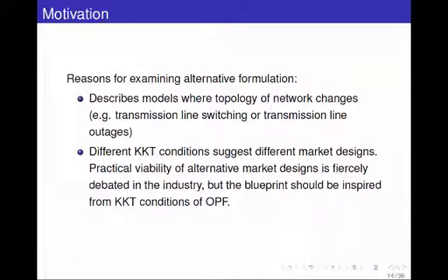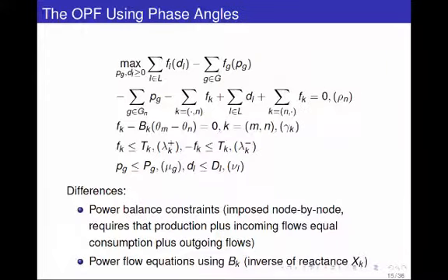And there's huge debates on which dual problem we should be using. Okay, the other reason for taking a look at this model is that we can actually model changes in the topology of the network. So if this line fails, we can model that using the reactances, because the reactance jumps from something positive to infinity, whereas if we're using PTDF and a certain line gets lost in the network, all the PTDFs change. So this model is also used for modeling changes in topology in the network.